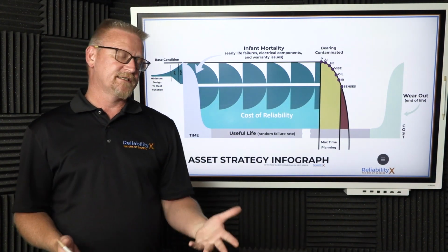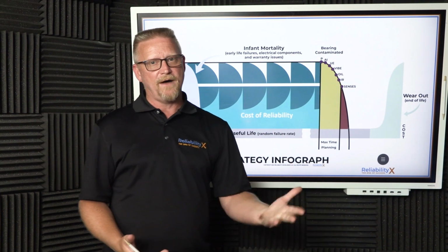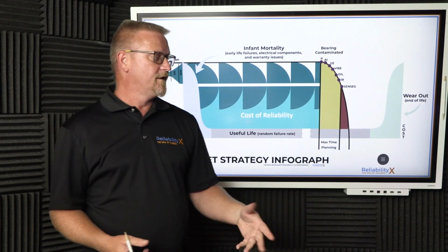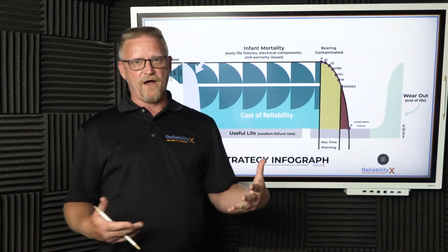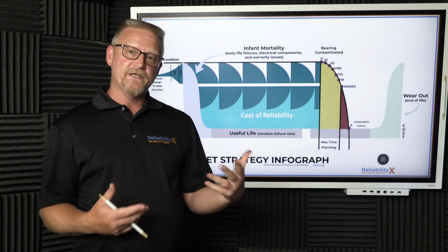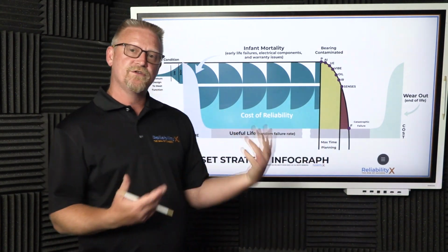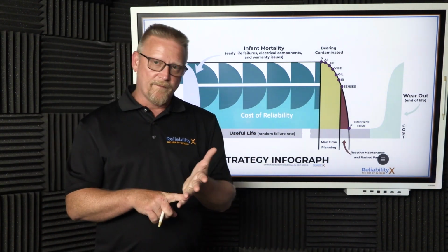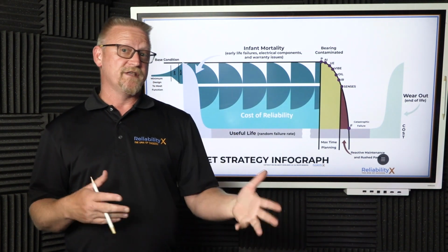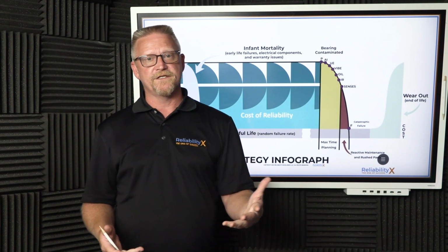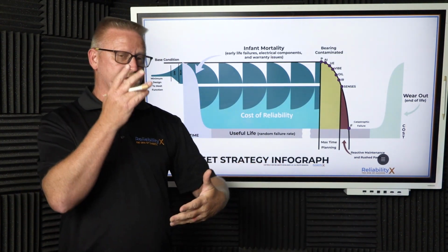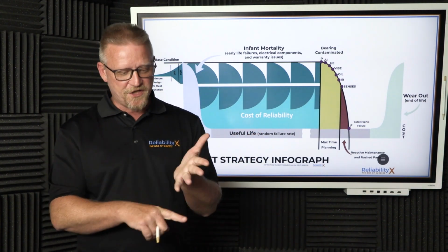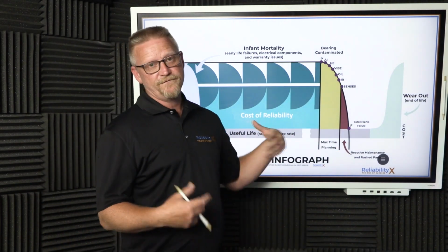We utilize predictive technologies to give us a window of opportunity in which we can properly plan, schedule, and execute the work before the major catastrophic event occurs. The reason we do this is to buy us time and to reduce the overall cost of the repair in terms of the operating cost and the just sheer other damage that could occur, right? If we don't use these technologies, what happens is the bearing blows apart, the shaft drops inside the pillow block, makes a nice oval, blows everything apart. Then we need a shaft and a pillow block and a bearing instead of just the bearing.